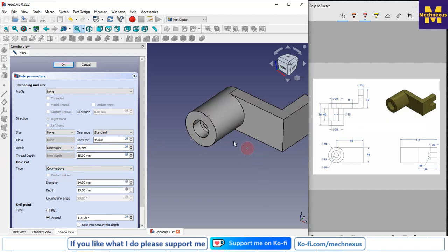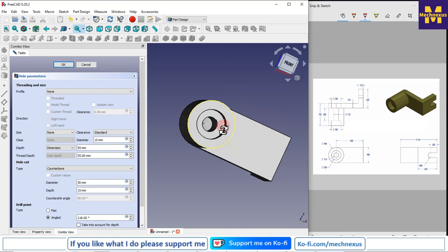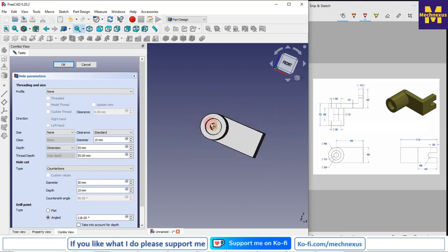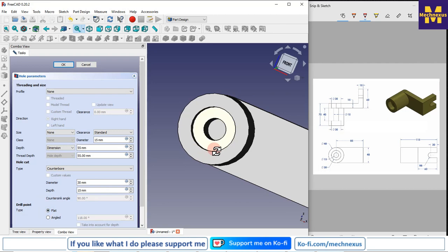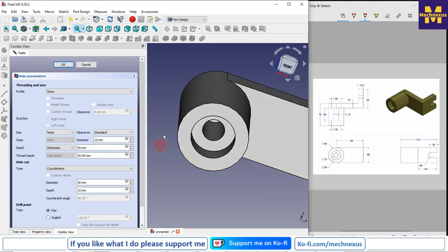Now here select the counter bore. Now we will give the diameter. Diameter one is 30, so we will give the 30 with the depth of 15 mm. Always note that your second diameter must be larger than your first one. So you can see that our counter bore has been created, and now you can see that here we are seeing the angle. To avoid that, you select here the flat, because our drill is flat here. Now say OK.